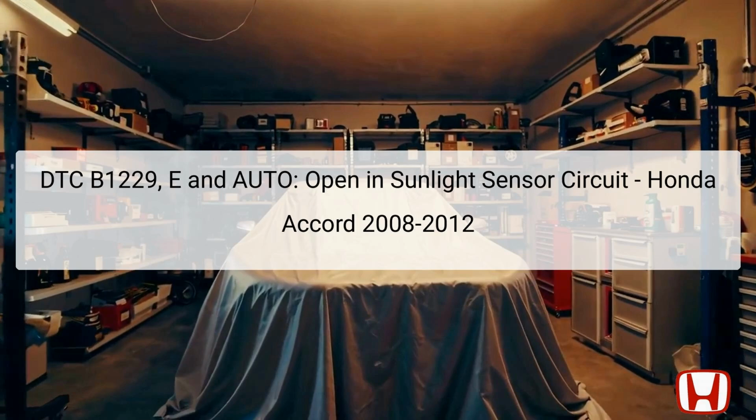The Honda Accord from 2008 to 2012 may display Diagnostic Trouble Code DTC B1229, which indicates an open in the sunlight sensor circuit. This code can be associated with the indicator E and Auto, which points to issues in the system that regulates automatic lighting and other climate control functions.